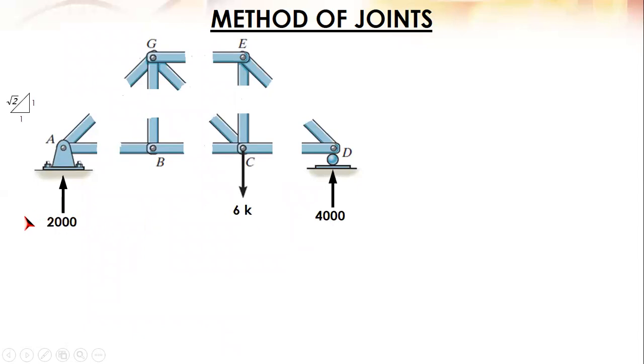And then same also with the reactions. So 2 kips and 4 kips. Okay. Let's start with joint A. So joint A has 2 kips upward. What balances this 2 upward? It's only the vertical component of EG. Horizontal EB has no Y component. So what balances the 2 is the vertical component of EG, which is 2.